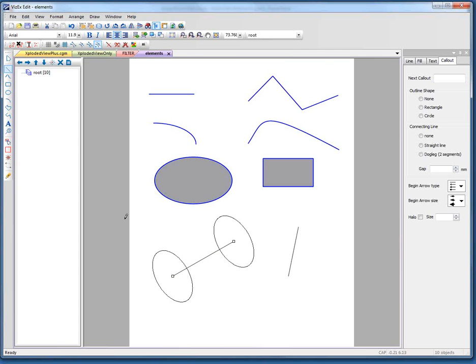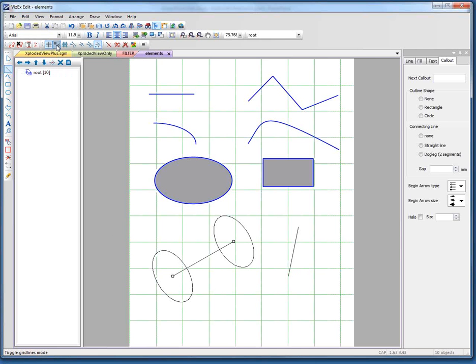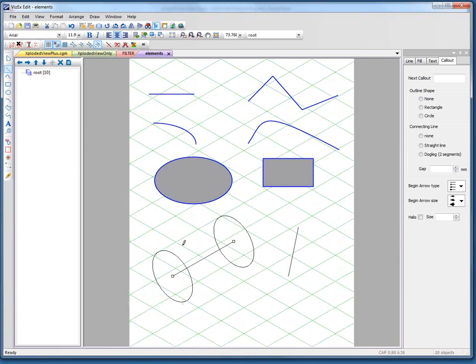And so this is a good opportunity now to show you the isometric views. So I'm going to turn on the grid lines. We have a toggle on the toolbar now to go between isometric and parallel grid lines. If we do that, you see how those ellipses align exactly with those grid lines. One nice application, I think, is to make those align like that just by duplicating. We know it's precisely aligned with the center of those ellipses, so it's going to align with their tangents automatically. So those are the snap-to functions and grid line control.